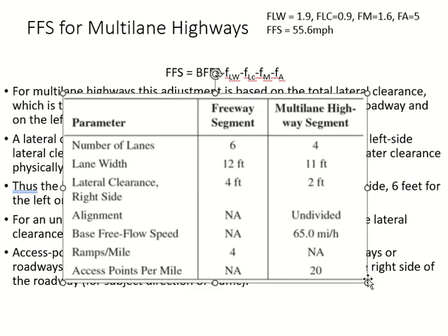Now you see some of the values are written non-applicable. For example, you look at this value. For freeway, they wrote it non-applicable. Now this value for multi-lane highway is telling us about what? Undivided means no median. So why it is not applicable to freeways? Freeways always have a median, so it cannot be undivided. There's nothing such thing as undivided freeway. If it's a freeway, it has a median. That's it. No other option. If you say it's a freeway, you don't have to tell me if there's a median or not. There should be a median.